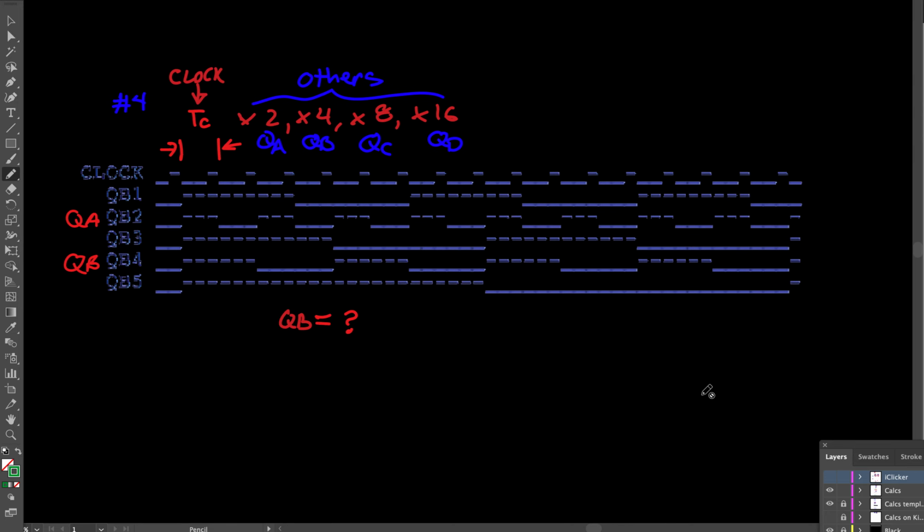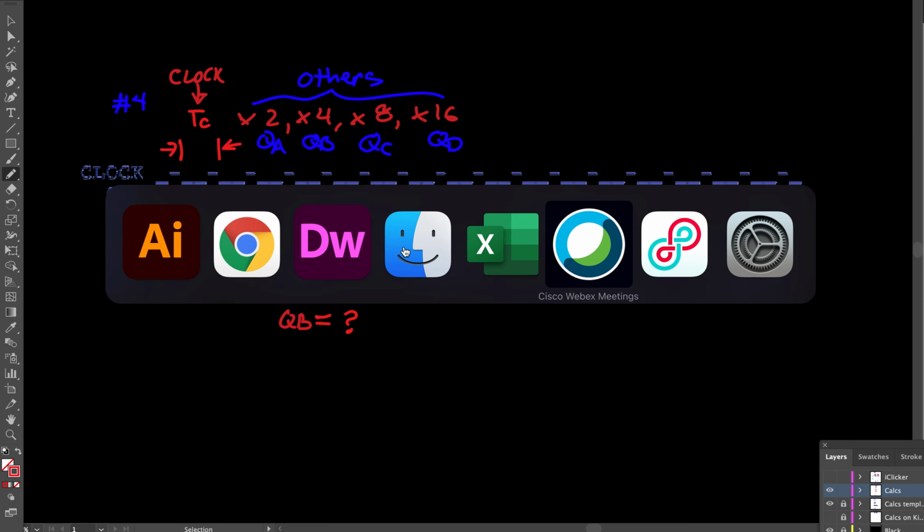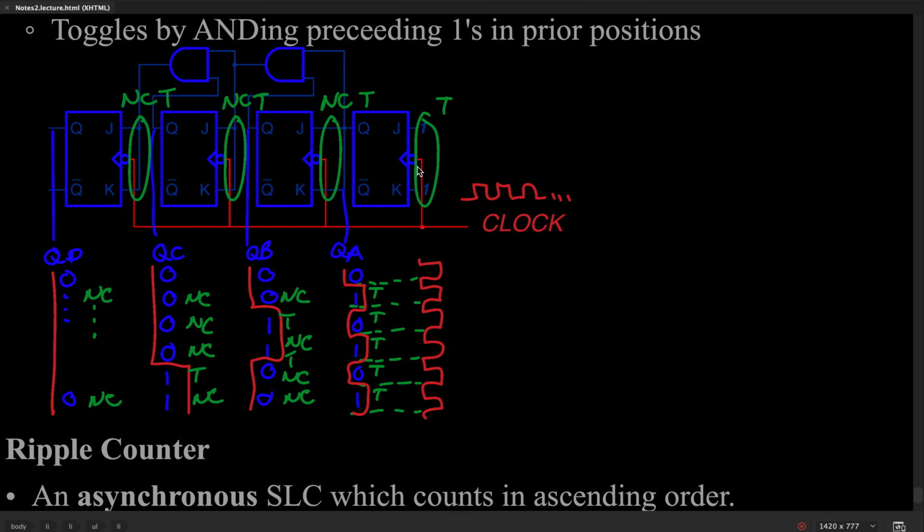And here it is. So in this particular case, the clock waveform starts here and it goes across. Then there are 5 waveforms below that, some of which are showing the answers that we want to see, and some of them don't correspond to anything that we want to see. We'll begin by taking a look at what the first waveform from the first initial flip-flop will be. That would correspond, in our diagram, to this picture here and this waveform here.